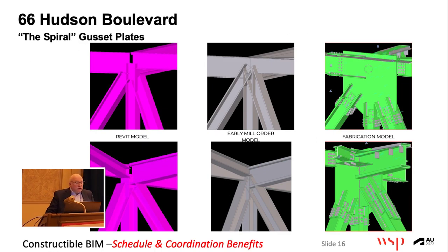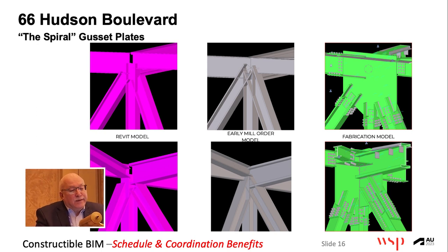So, schedule benefits. Now it becomes a bigger picture. Framing adjustments and inaccuracies are refined at this stage, not in the shop drawing phase. Connection design is based upon the actual member positioning, not an anticipated location that is not buildable. Now the connection design and review is removed from the shop drawing phase. It's pushed early, into the early stages of design. Constructability issues are addressed before they become a problem, before they delay the fabricator.